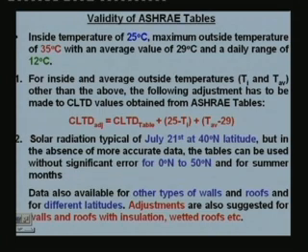Okay. So if you look at the ASHRAE handbooks or other air conditioning handbooks, all these tables are given, either CLTD tables. If you look at other handbooks, they give what is known as effective temperature difference tables, as a function of the type of the wall, orientation, solar time, and all that for fixed conditions. And they also suggest adjustments for other conditions. Okay, so if you have the tables and your specific conditions, then you can get the tabular value, apply the adjustment and get the adjusted value of CLTD or ETD. Okay, that one must use for calculating the heat transfer rate.